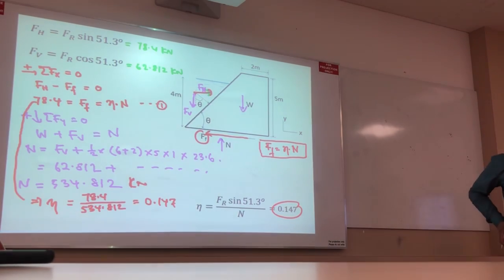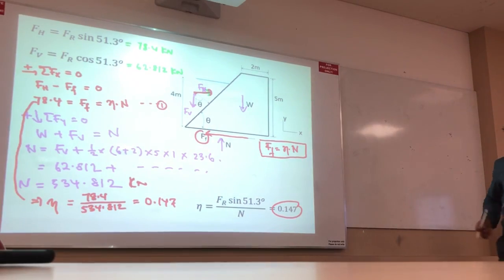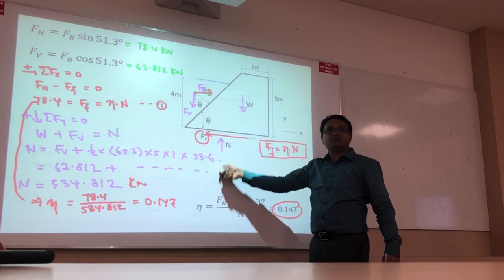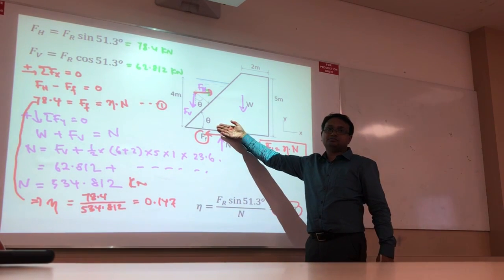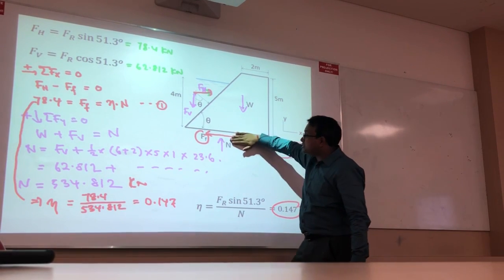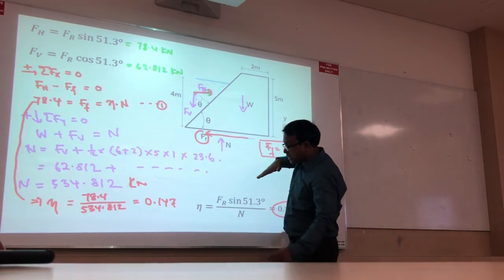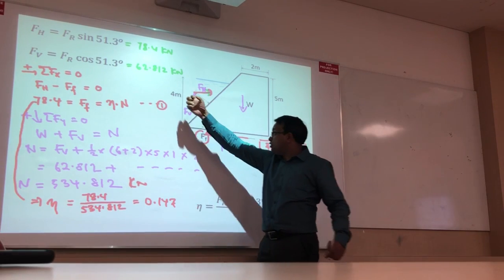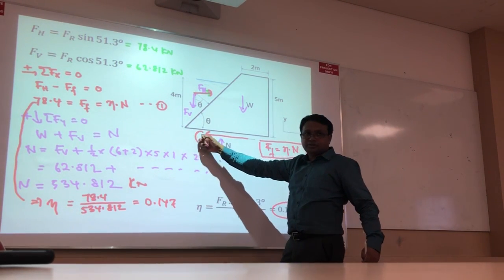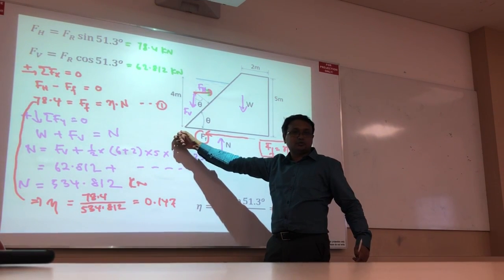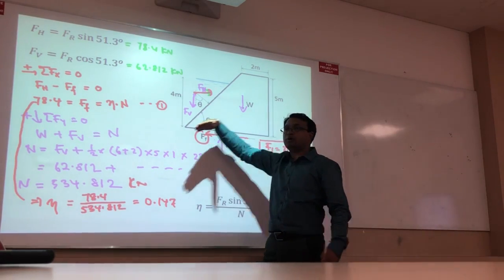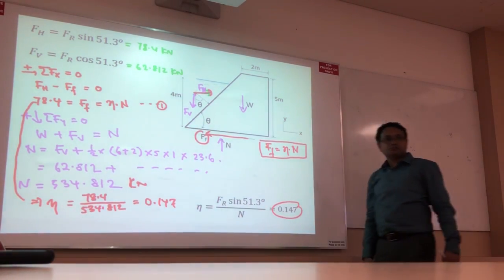Alright? Why is there a normal force? Because the weight is there, definitely there is another force on that area. Otherwise, it will not be balanced. And there is a frictional force here because it is sliding in this direction. Because of the water force that acts in this direction, there is a frictional effect, which prevents the dam from sliding from the top to the water. Okay?